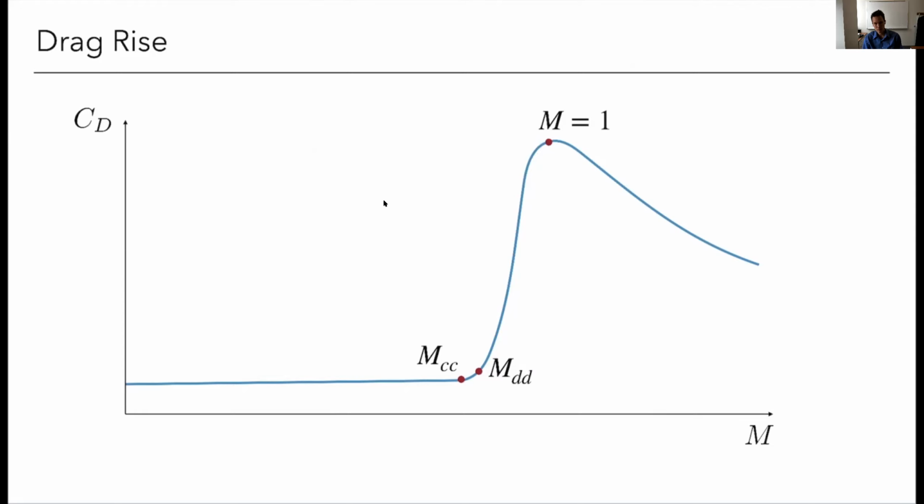Although it was common or maybe popular to think that before we crossed the sound barrier that people thought it was an actual barrier, we knew, of course, long before we flew past the speed of sound that this was not an actual barrier. Projectiles had been shot faster than Mach 1 for quite some time before that, but for aircraft, it's still called a barrier in the sense that this is a lot of drag you have to overcome, right? But the drag coefficient, not necessarily the drag, does start to decrease again, right? And it generally peaks around Mach 1.